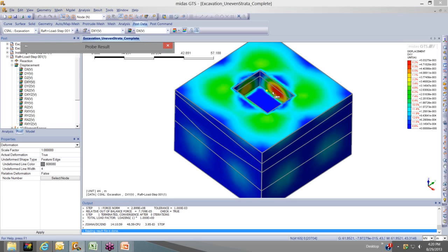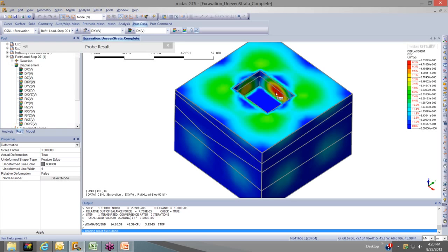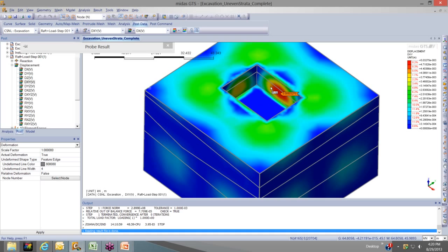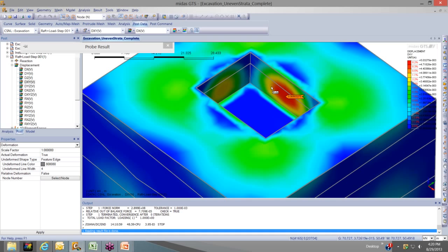And what you can do, just using your cursor, is double-click on certain portions that are available to you. Let's say, for example, you zoom in, and maybe this yellow area is of interest to you. You want to see the displacement over here because it looks like that's where you get your maximum range of displacement. So double-click, and you can tag, just going along here, your different displacements. And then just using this legend here, you can see your exact numerical values, what your units are, etc.